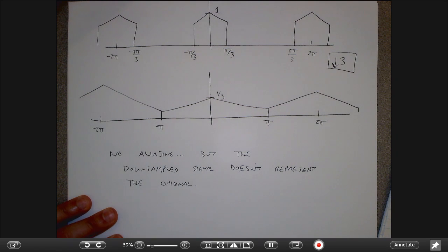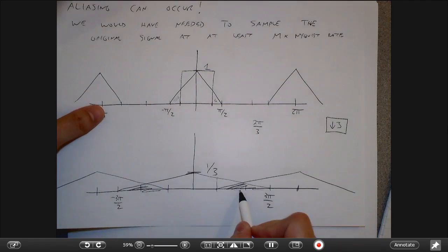Right? And actually, if you remember when I was showing you the music example, the sound sample, that's exactly what I was talking about. The original sound sample was sampled at 44 kilohertz, and I was changing the sampling rate. Even by downsampling by a factor of 2, certainly there are high frequencies that the human ear could hear that are going to get aliased into the audible band.